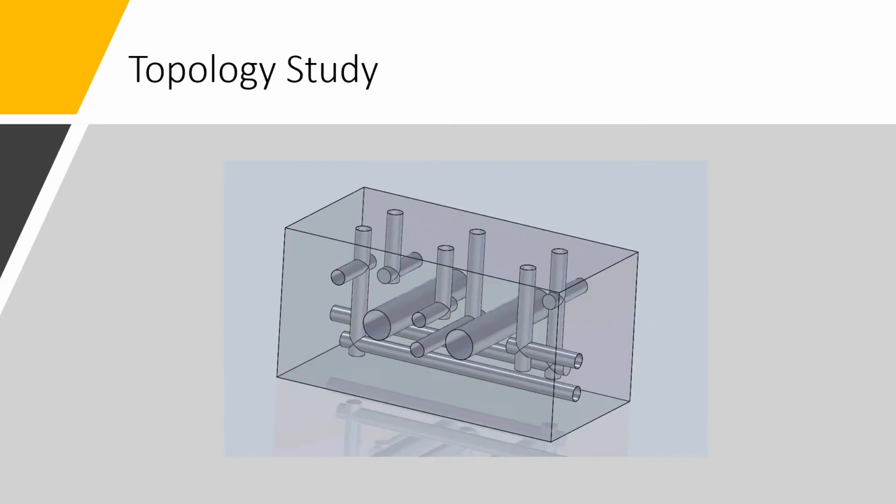Subtractive manufacturing techniques result in an abundance of excess material, which is surplus to the requirements. Additive manufacturing allows a topological optimization study to be carried out on the component in hand to understand the areas of material which can be removed, while still allowing the manifold to meet all required constraints. Areas such as this here can be removed to optimize the design.